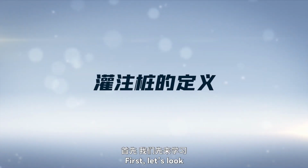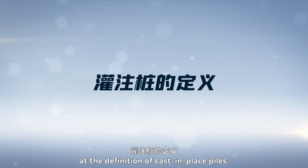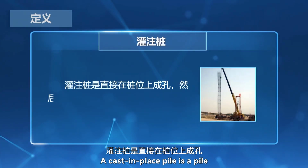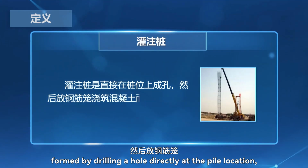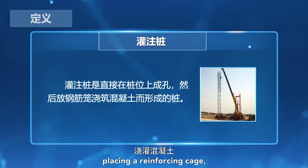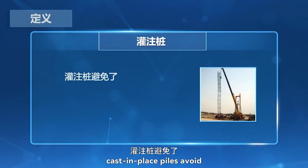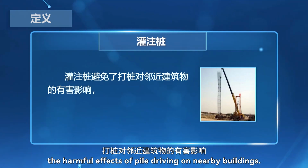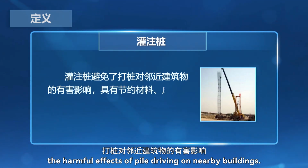First, let's look at the definition of cast-in-place piles. A cast-in-place pile is a pile formed by drilling a hole directly at the pile location, placing a reinforcing cage, and pouring concrete. Compared with precast piles, cast-in-place piles avoid the harmful effects of pile driving on nearby buildings.